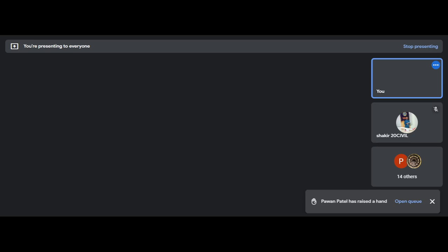Then we saw the elements of waste management system. This included the six elements. It had generation, collection. Then we try to separate the waste. Multiple kinds of separation are there. We can separate at the source also, and we can separate properly in a facility. After separation, we have transport of the waste. Then the waste is collected. It can be processed, so there is the processing stage. Finally, we will have the disposal stage. Based on the city, one or two of these stages can be absent also. So these are the six elements that will usually be there.